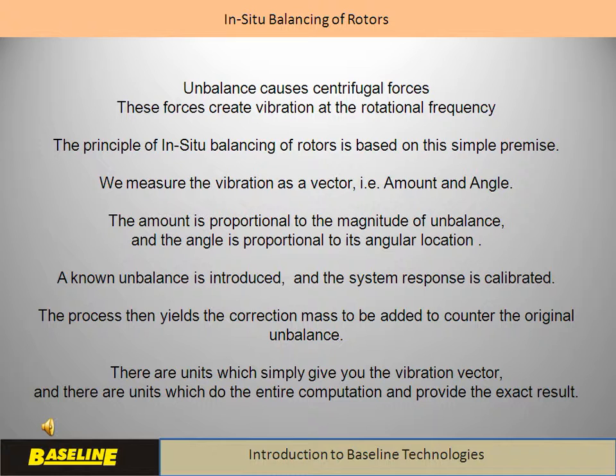The amount is proportional to the magnitude of unbalance, and the angle is proportional to its angular location on the rotor. A known unbalance is introduced and the system response is calibrated. The process then yields the correction mass to be added to counter the original unbalance.